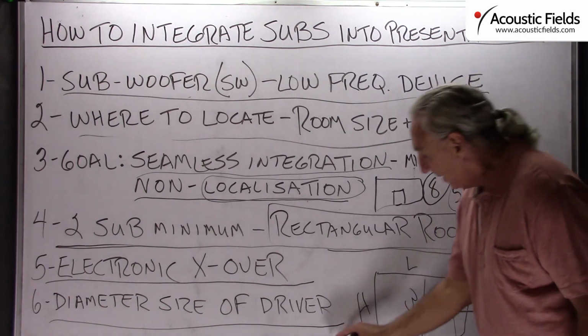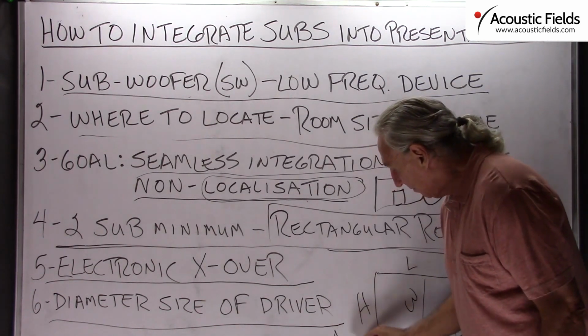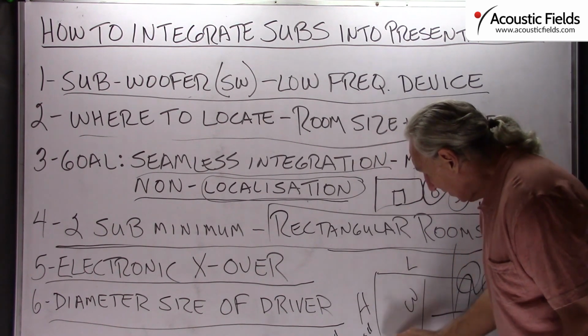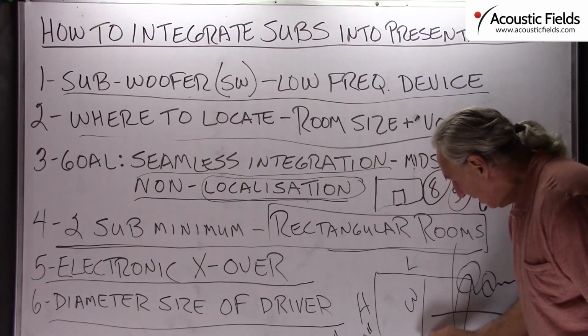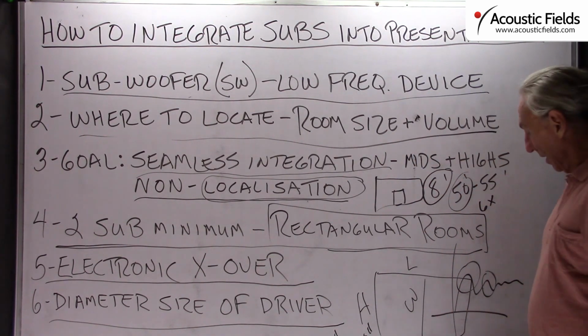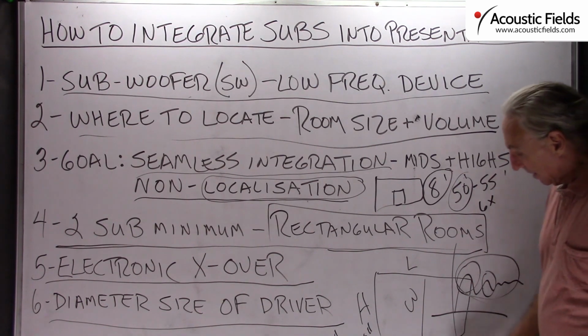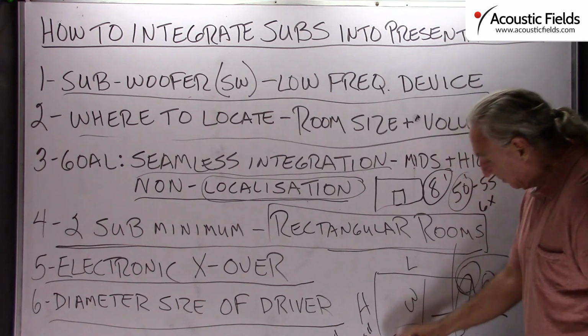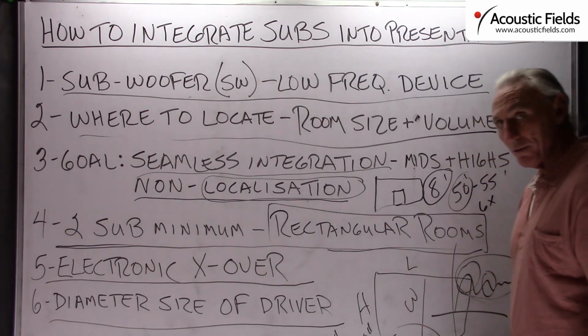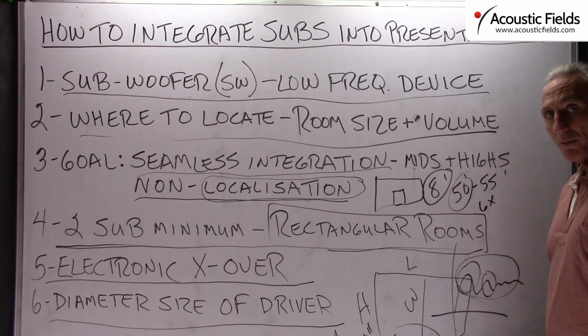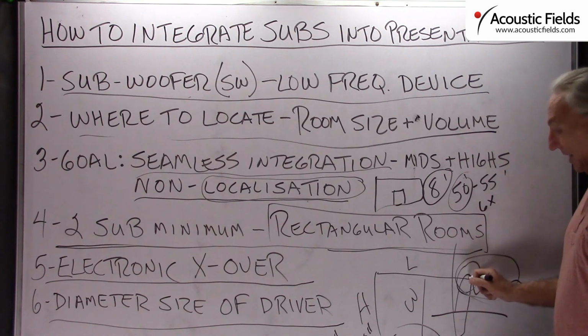You have to realize that a 10-inch driver versus a 12-inch driver, there's a plus 2 dB gain differential. So whatever problems we're exhibiting that are untreated in our room, we have to be careful about adding another 2 dB of energy by picking a driver size that's too big for the room volume. So we don't want to exaggerate.